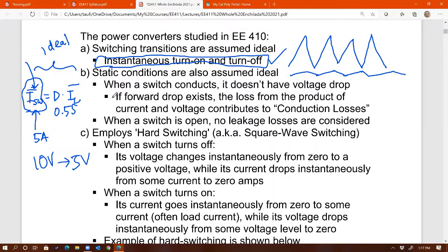I had a quick question about before. The static power, why is it not dependent on frequency? Is that just the real part of the static power of the MOSFET being taken? Yeah, it does not depend on frequency because it relates to when the current is at a constant value as well as voltage at a constant value.